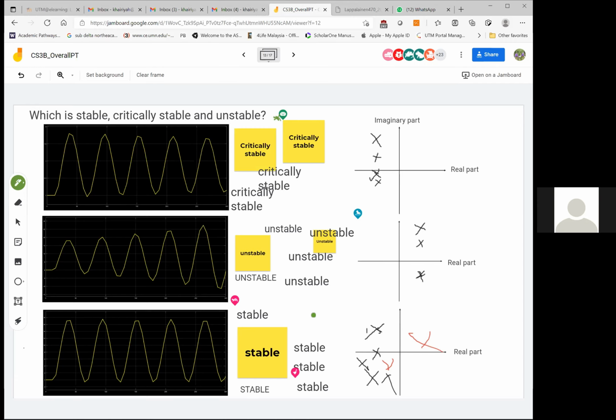Doctor, does that mean there are no errors? Zero errors here? Doctor, is it going to stable? Critically stable is when if you increase the gain even a little bit, after that it becomes unstable. Okay, it's on the borderline, just before instability.